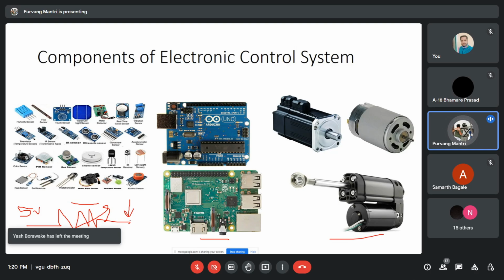There are formulas already developed, so we know that for this much change, for this much voltage, this is the output value. For example, if it is a temperature sensor and the temperature rises, its resistance is going to reduce. If the temperature falls and it becomes colder, its resistance is going to increase. In a chilled region, the highest resistance is applied over this circuit, and 5 volts is going to reduce down to 0 volts.